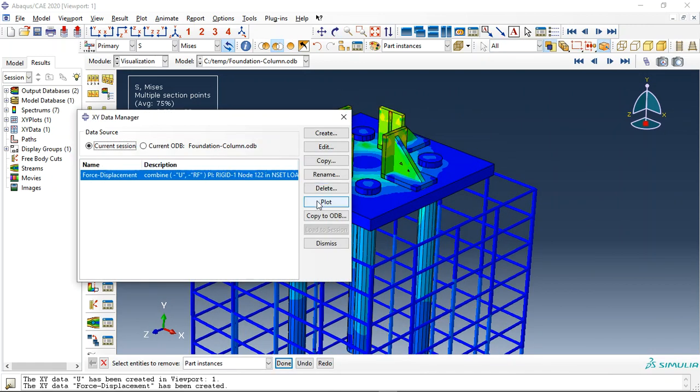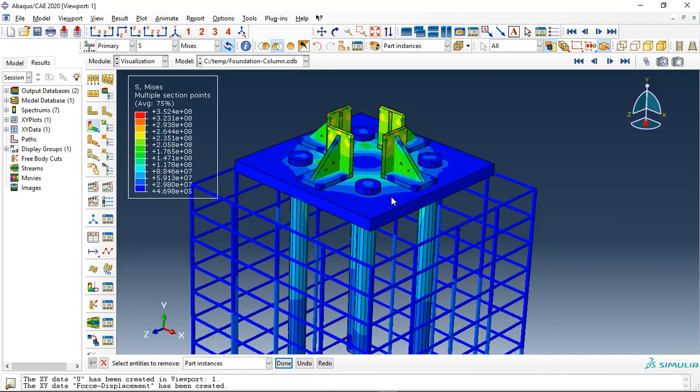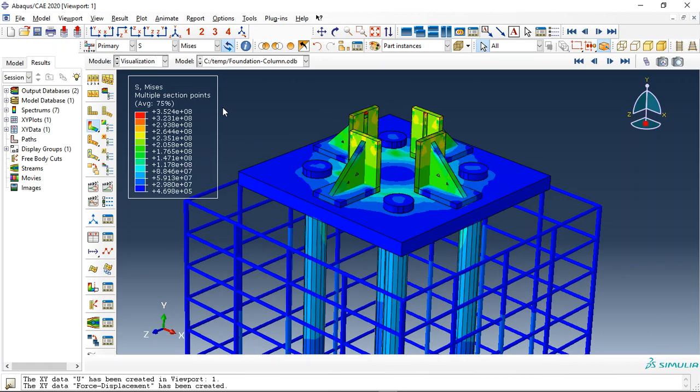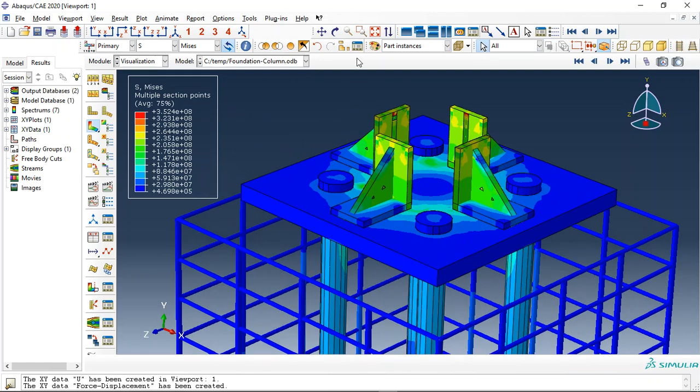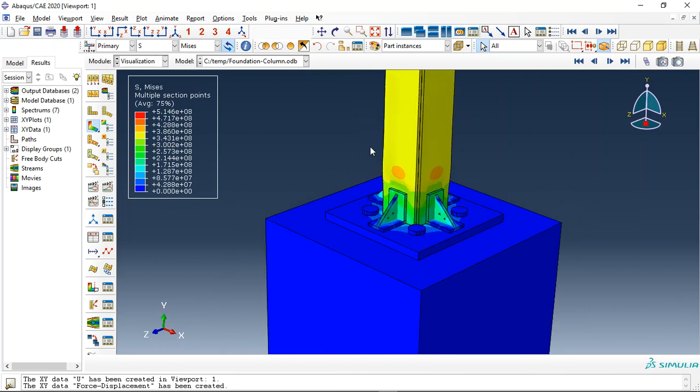And if I draw a force displacement diagram, you see this is the force displacement diagram for this model. Here is the peak, then we have engagement, it is increased till here. Here we have a decrease in the force capacity. If we keep the displacement or load, it will reach zero value for the force, and it means it is failed completely. You can see it here.